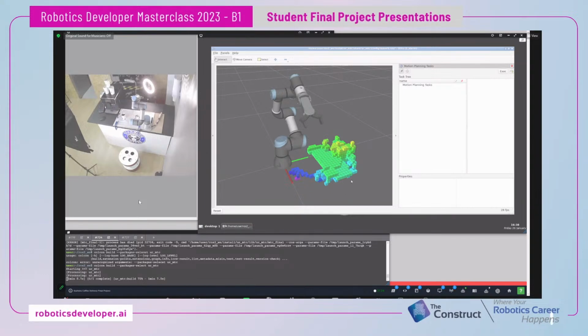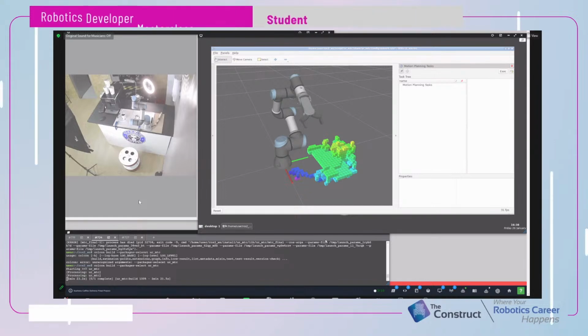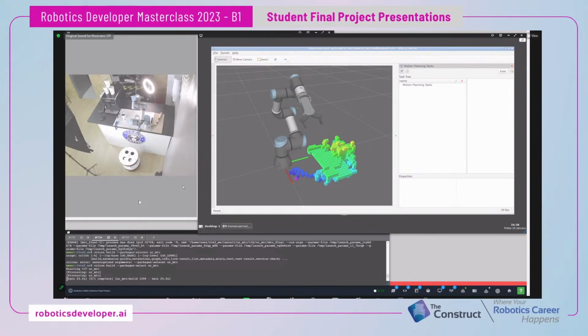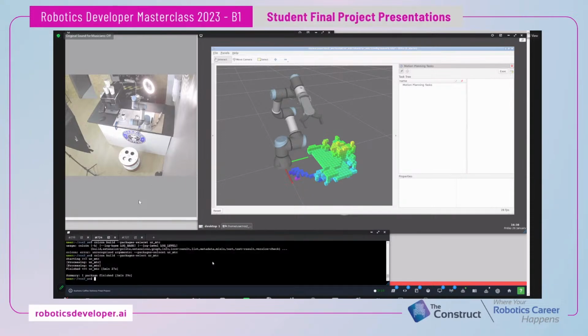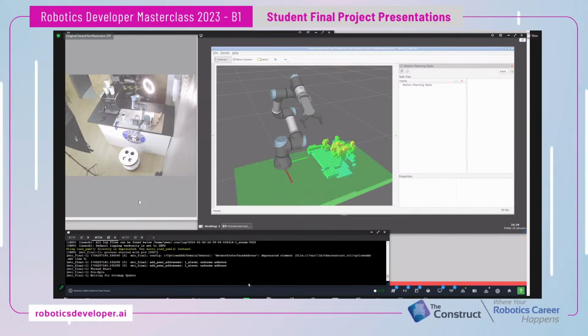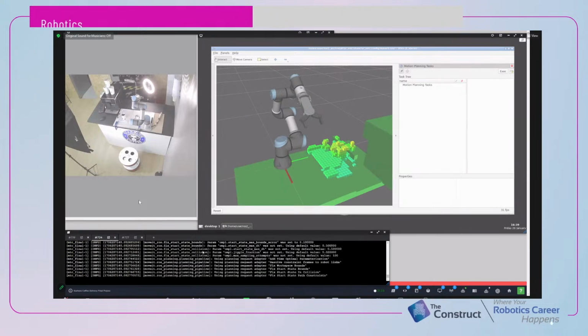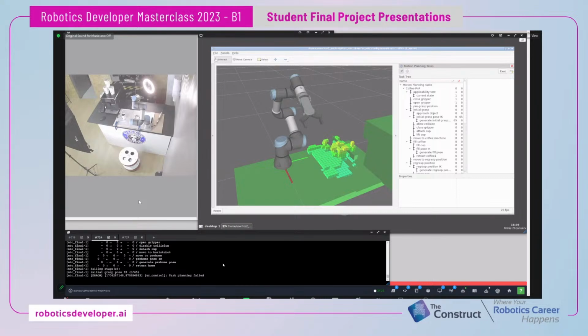The precision available to find the center point of that circle is much higher than what's available converting a depth camera to point cloud and doing all of that processing. So that would be one thing that could be done to ease some of the computational load and actually make it more precise.